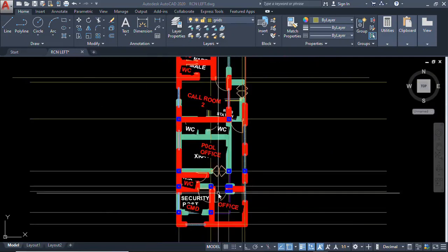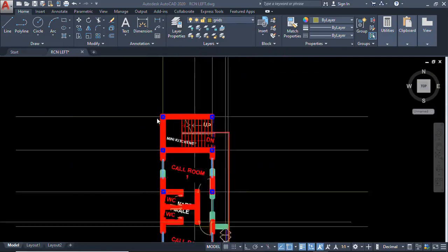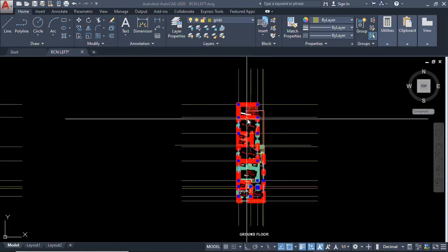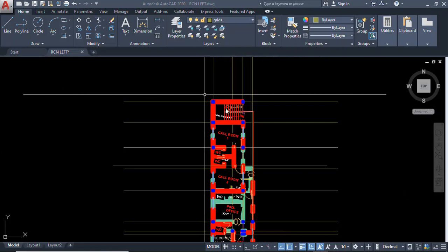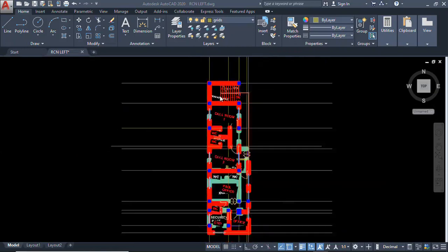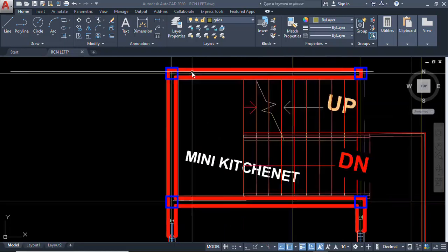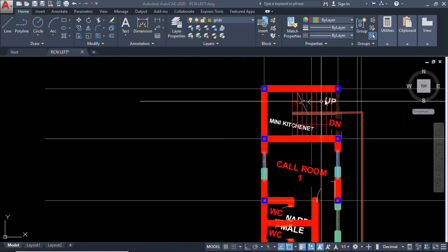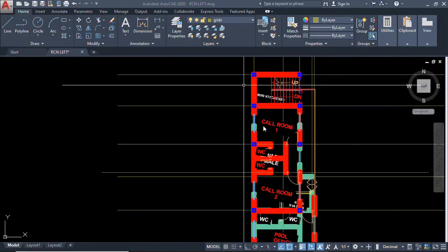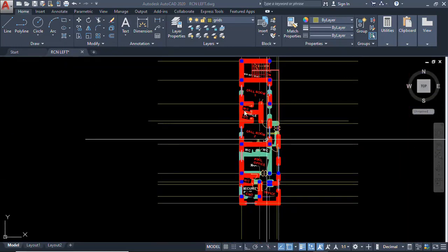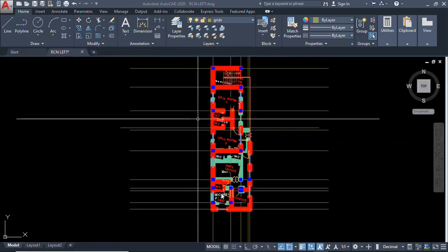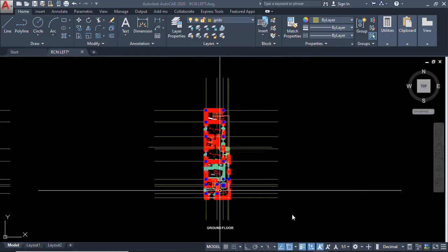So in the last lecture I showed you how you can check your drawing. You can check whether the ground floor and the upper floor are the same by changing their colors, and how you can insert your columns, put your columns and grids in layers, and prepare your GA placement of your columns just like this, and how you can save your drawing as a DXF so that it will be recognized in Prota Structure.